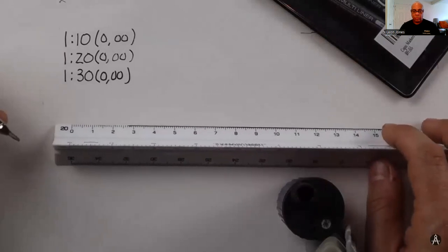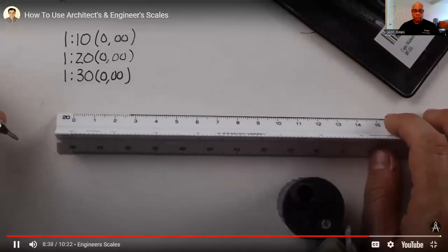And I wanted to draw a line that was... And again, before continuing, he's on a 20 scale. Well, look at the graduations. Graduation is what we call tick marks. It's 20 graduations per inch. You have 5, 10, 15, 20. That's an easier way to understand the engineer's scale.